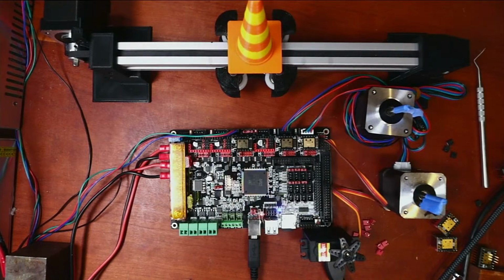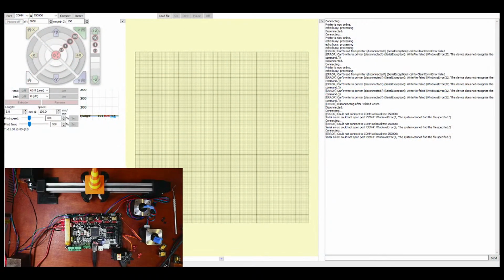And then I'll go over to Pronterface. Inside Pronterface, I'll try and connect again. And it's online. Let's try that. M280 P0, P0 being the first servo, which we only have one in this case. And then I'm going to say S80. And that's just going to move it, I hope. So it didn't work.